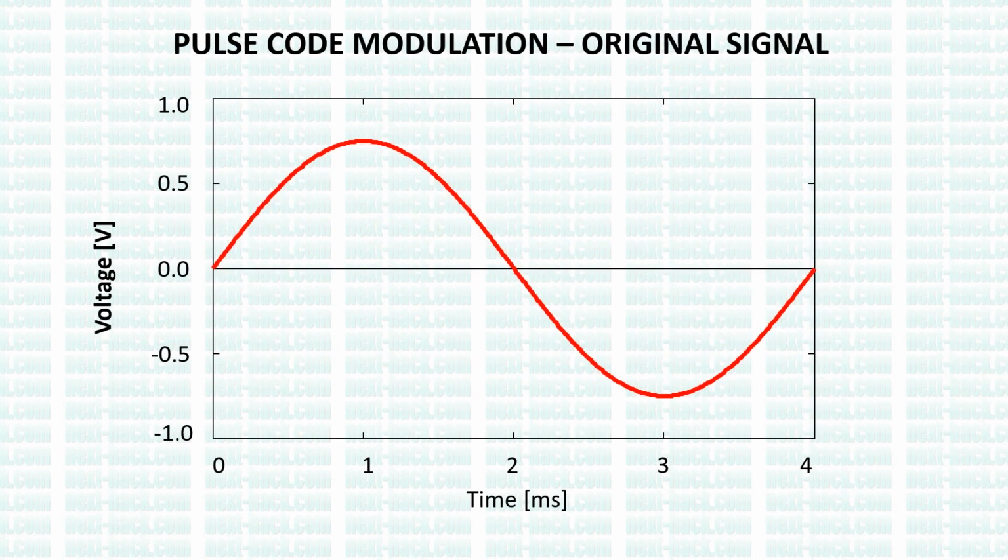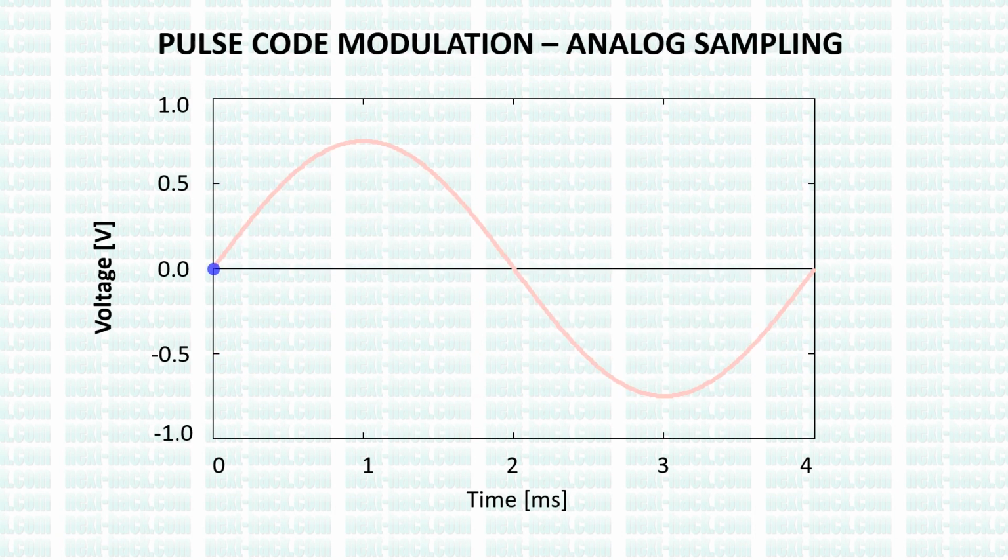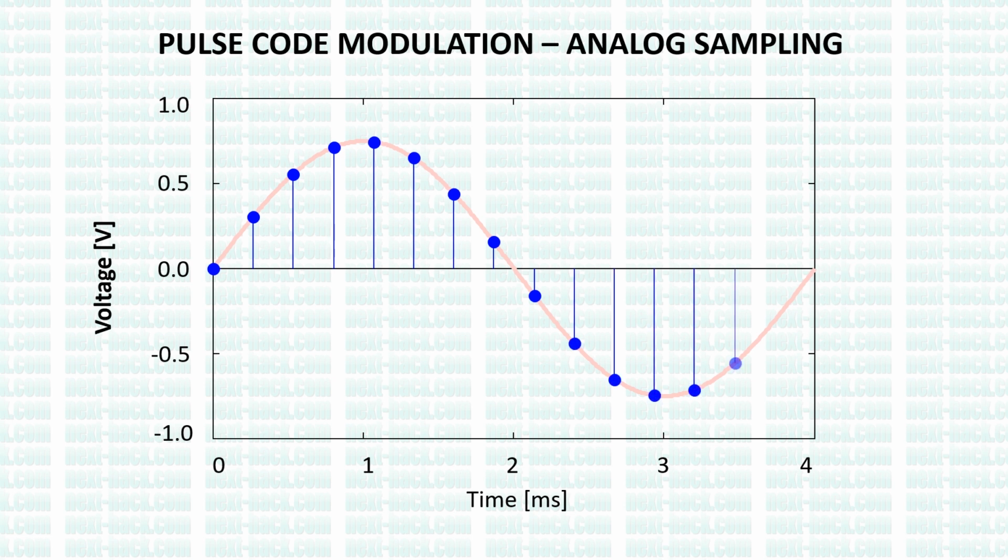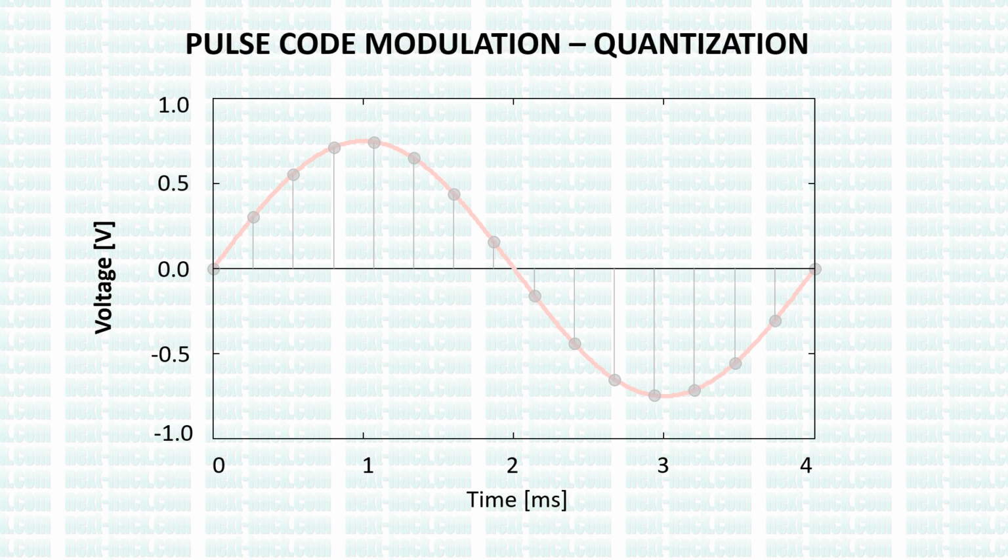Storing and playing audio is usually accomplished by using a technique called pulse code modulation, or PCM. The signal we want to store is sampled at regular intervals. The sampling frequency is called also sample rate. Now, instead of our audio signal, we have a series of pulses, hence the name pulse code modulation. Each of these pulses cannot be stored yet in a digital form, as they must be quantized.